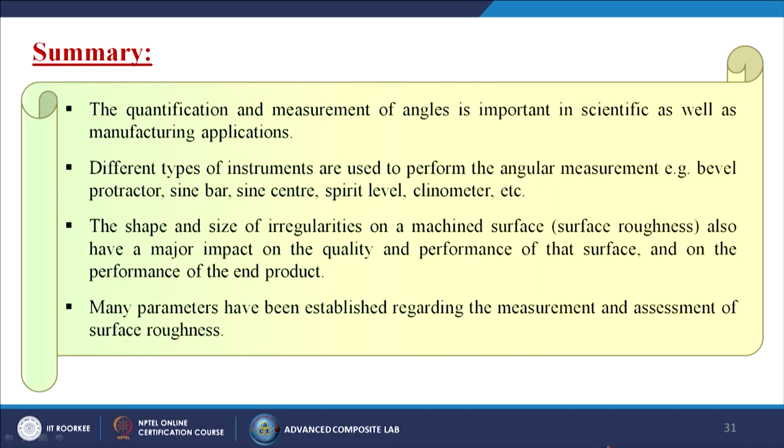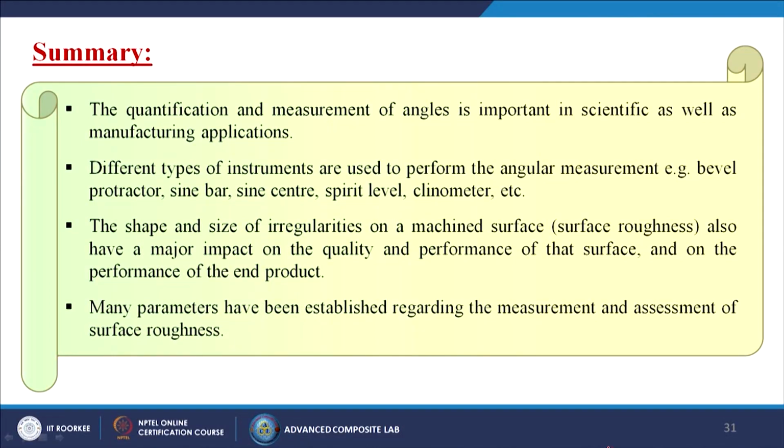Now, we have come to the last slide of this lecture. In summary, we can say the quantification and measurement of angles is very important, as I told already, because when we need to make conical shapes or helical shapes or contour shapes, measurement of angles is highly required. So, different types of instruments are used to perform angular measurements, like the bevel protractor, sine bar, sine center, spirit level, clinometer, etc., which we have already discussed.